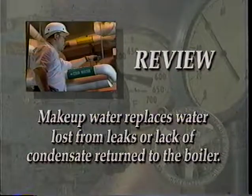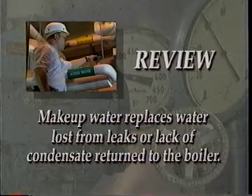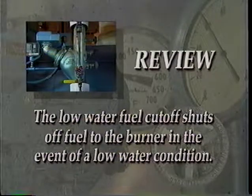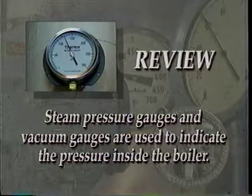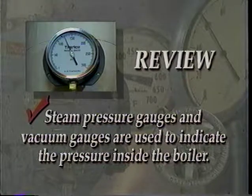Make-up water replaces water lost from leaks or lack of condensate returned to the boiler. The low water fuel cutoff shuts off fuel to the burner in the event of a low water condition. Steam pressure gauges and vacuum gauges are used to indicate the pressure inside the boiler.